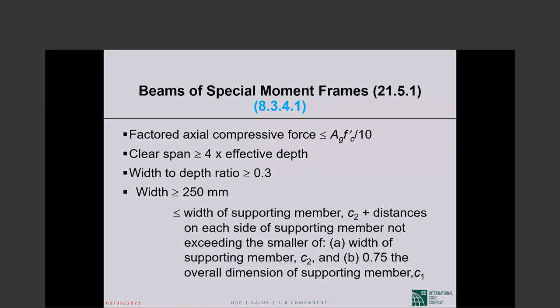They are used all the time. And I also mentioned they are used in conjunction with 100% lateral force resisting shear walls, or sometimes it could be steel brace frames. So it is not that flat plate column frames cannot be used in design category D buildings. I never said that. Nobody has ever said that.